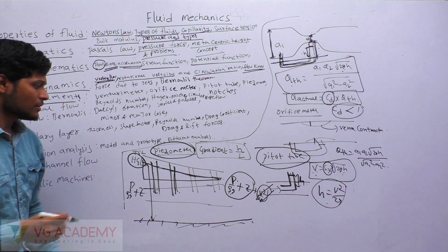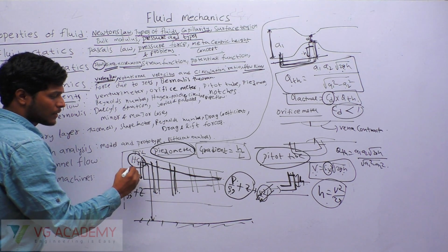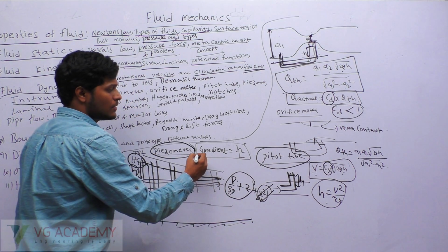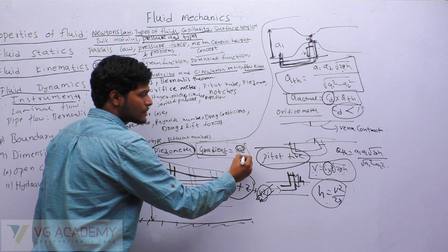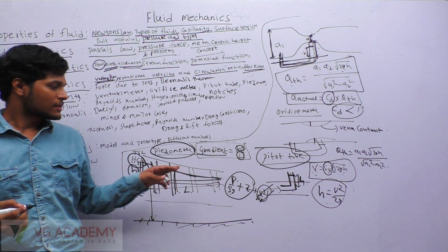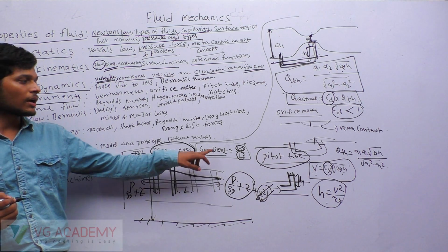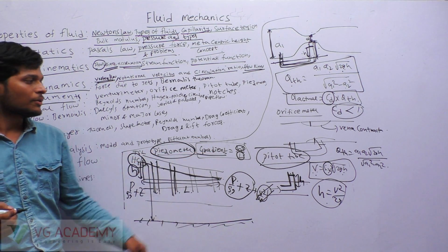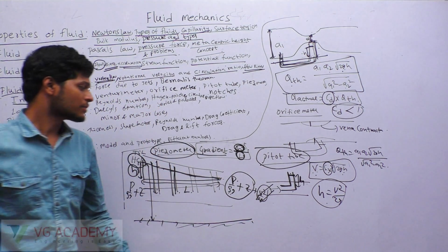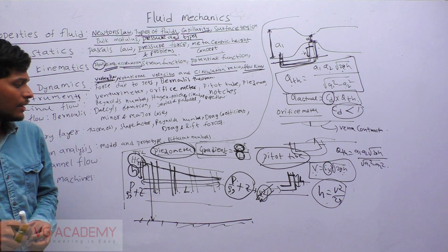So here this is the origin. So what is the value of y? Nothing but head loss divided by length. Okay. So the gradient is head loss by length. Okay. So this has a different name, as this is the loss in the water. We call it the hydraulic gradient, which is given by head loss per unit length. Okay. So that is called hydraulic gradient.